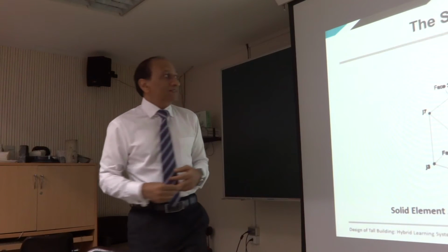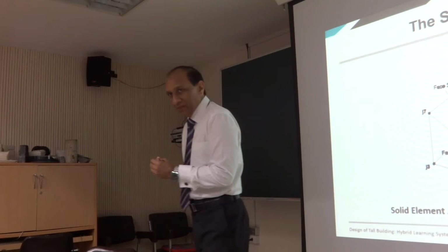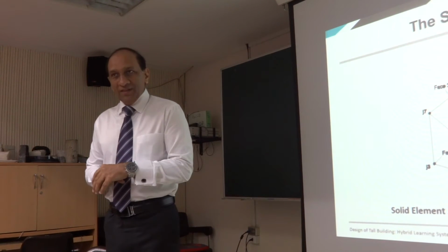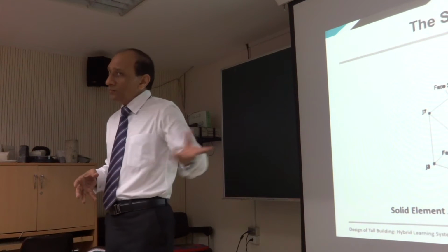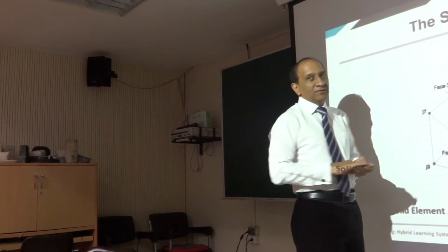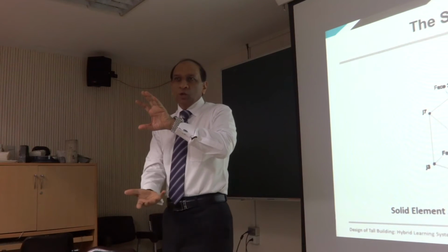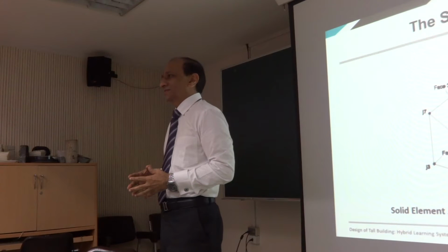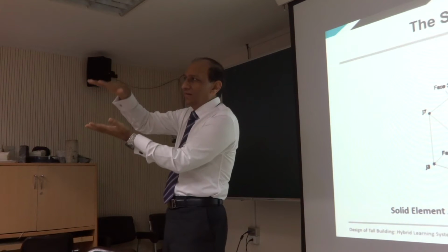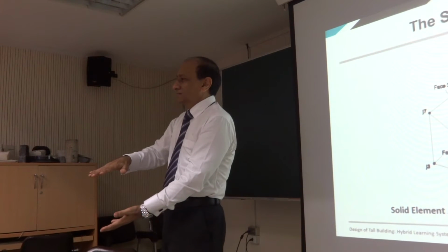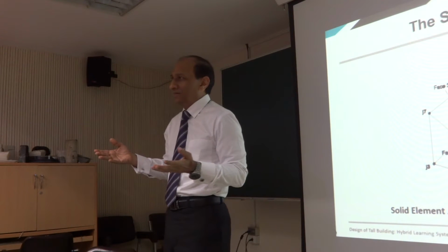So that's why solid modeling is really good, really nice. It can serve many purposes as long as we know how to do it. And it has very few properties, no dimensional properties, only material. But material can be very complex. Now we can model, come back to my original thinking what I was telling you about. Dam, water, gates, soil, all modeled as solid elements, right? And soil also, you can model layers of soil, sandy layer, clay layer, different layers, right? Even air can be modeled above that. Why not? Air is nothing but solid elements with its own properties.